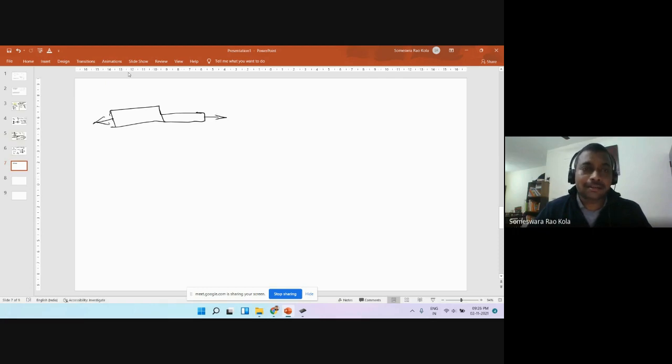In this case, of course, we can use a cover plate and another cover plate like this, but we have a gap here, so we are going to use something called packing. This is called a packing plate, because we cannot leave the gap and then have a bolt here. It has to have some kind of support. So we use a packing plate like this.